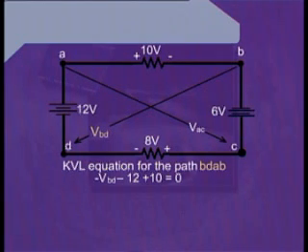After reaching point A, we will be facing towards point B. And also we can see that there is a resistance between points A and B. The voltage drop across this resistance has been given as 10 volts, whereas the terminal towards point A has been marked as plus. Therefore, we will write plus and the value of the voltage drop across the resistance, which is 10.